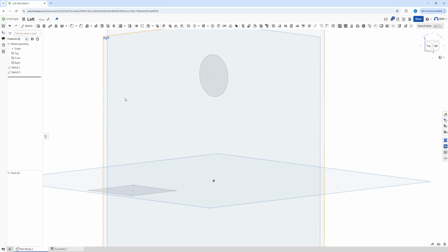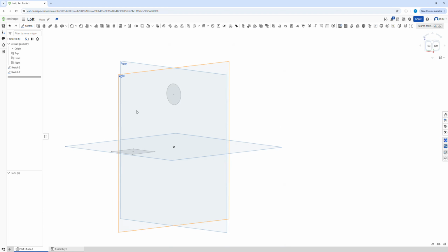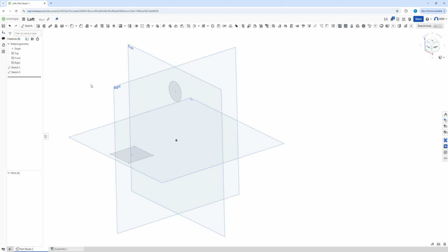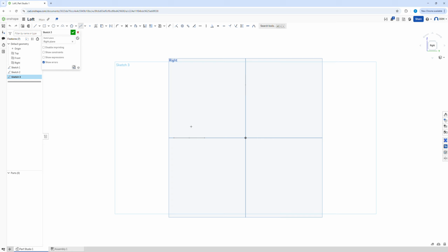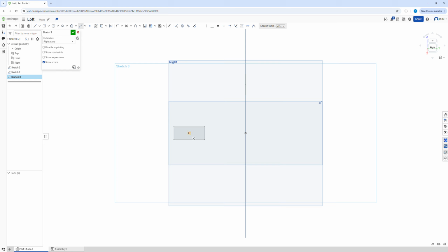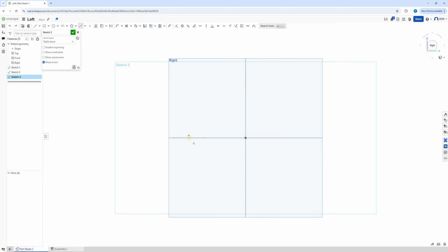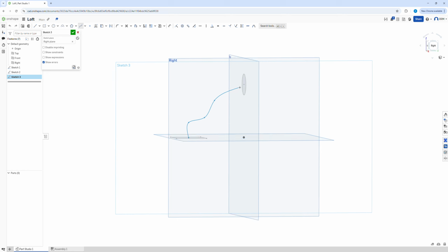I'm also going to show you something else. You might want to add a construction line or a guideline. So on this plane, I might want to take my sketch and let's go for something a bit random. Take another spline here, normal to. From the midpoint of our rectangle, or our cube, sorry, our square, we can click, drag up, make a few random lines, and then go over and join to that middle part there.